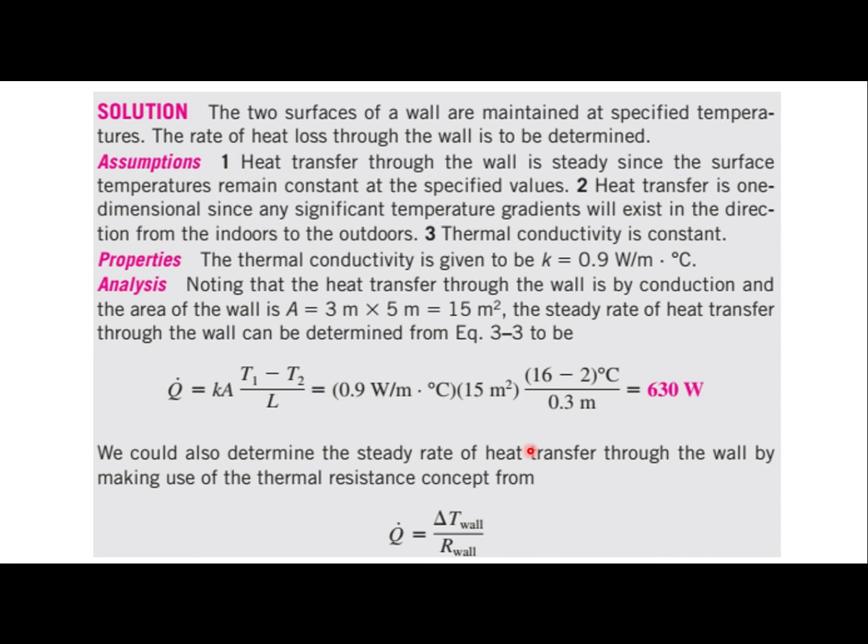There is another way to solve this problem. We could also determine the steady rate of heat transfer through the wall by making use of the thermal resistance concept, and this is the equation that we studied in the previous slide: the rate of heat transfer is directly proportional to the temperature difference and inversely proportional to the resistance.